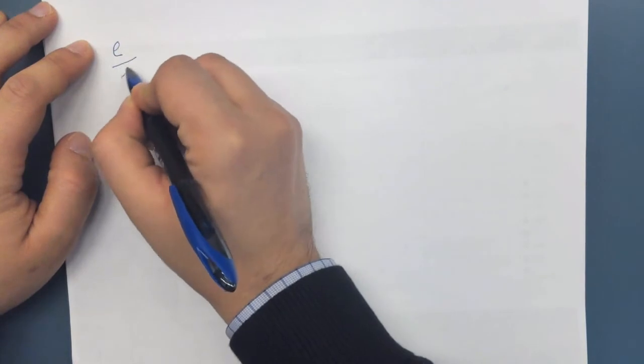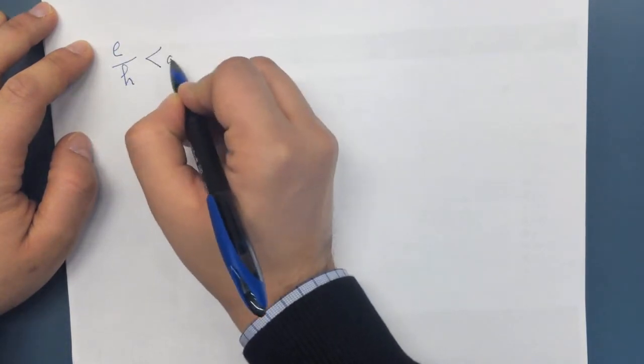So in reality, every section can have both axial load and bending on it. But in practicality, we can ignore bending on some sections. The code tells us that if e over h is less than 0.1, we can ignore the bending.